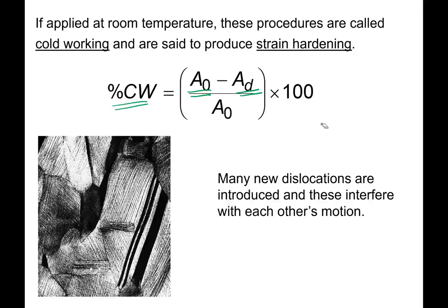All right. So the issue with having too many dislocations is that they start to actually interfere with each other. So a certain number is fine, and the material can be very ductile. But if you start getting too many and the dislocations start crossing each other, then those stresses around the dislocation core will start interacting with each other, and you get the repulsion we talked about. And depending on how these are slipping, it can actually produce dislocations that can't move. And so that's the mechanism for the strain hardening. It's just too many dislocations start to get in each other's way, if you want. They interfere with each other's motion.